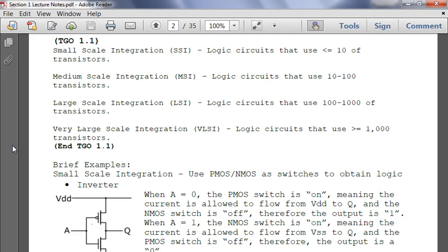So we're going to define a pMOS transistor as a strong passer of ones, meaning that this is what's known as the gate. When a 0 is put on the gate of the pMOS transistor, it will pass whatever value is on the source to the drain. Here, we have it hooked up to 1. So if we put a 0 on the input, it's strong.